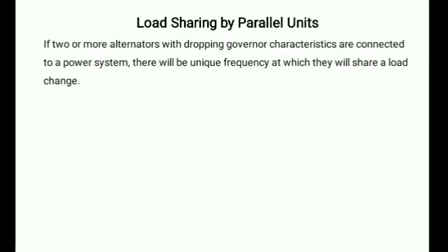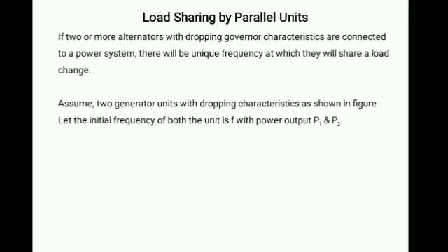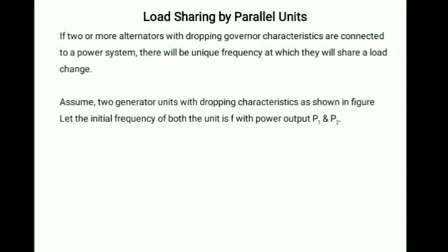Now let's start with the next topic, that is load sharing by parallel units. This is one of the important topics in LFC, load frequency control. Let's take two generators having different drooping characteristics which are connected to the power system. We can take more than two alternators also, but in this example I am assuming two alternators, and let us assume that there will be a unique frequency at which they are capable of sharing the load.